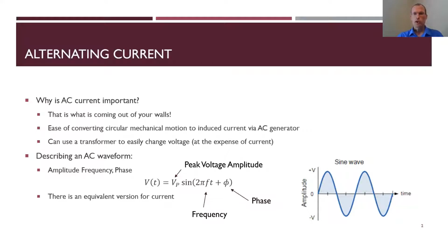So generally, your voltage or current source has a sinusoidal waveform, such as the one shown down here. So my voltage as a function of time is some peak voltage, Vp, and then the sinusoidal variation, 2 pi times the frequency, generally in hertz, times the time in seconds, and then your phase shift, if you have one. A similar equation for current: you have some current as a function of time, which is some peak current, then you get some sinusoidal variation. It's pretty much the same.